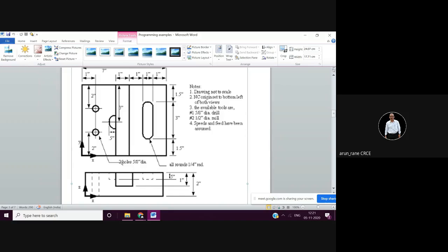After this, you lift the cutter. Okay, so G0 Z 2.2. Now let's bring the cutter here, exactly at the center of this. Z is now: the cutter is 0.2 above this surface. What is this dimension? X 5.5, and this will be Y 3 inch. 1.5 plus its half, so Y 3 inch. X 5.5, Y 3 inch.